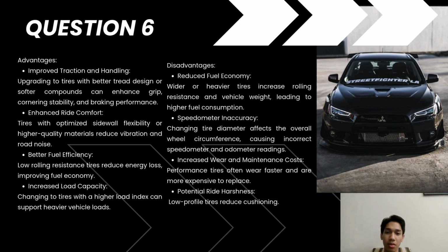The wider or heavier tires increase rolling resistance and vehicle weight, leading to higher fuel consumption. Next, we have the speedometer accuracy. Changing tire diameter affects the overall wheel circumference, causing incorrect speedometer and odometer readings.